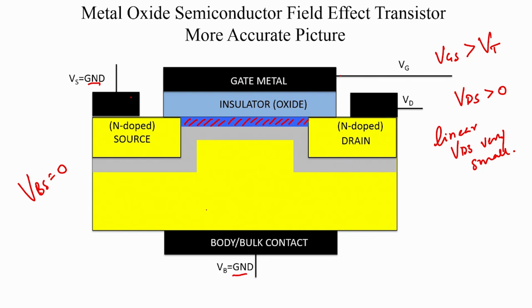But what we did not show in the previous picture was the depletion region. If you remember the MOS capacitor, you first deplete the semiconductor, and it is only after the semiconductor is depleted that you form the inversion layer. So, you have two regions here, the inversion layer and the depletion layer, and in the previous pictures this is not made very obvious. So, I am trying to make this quite clear here.